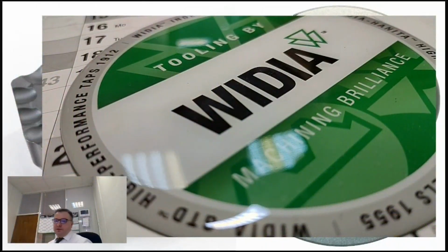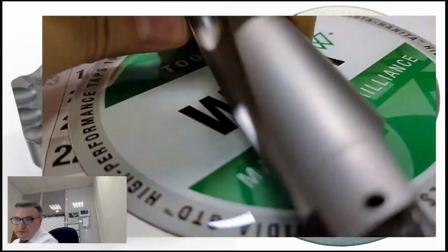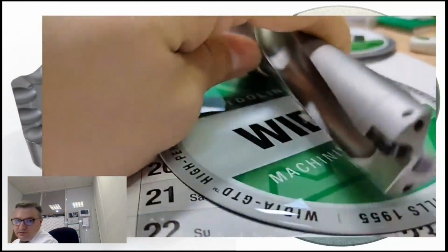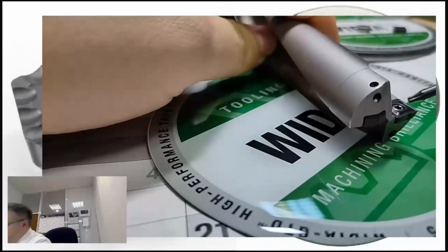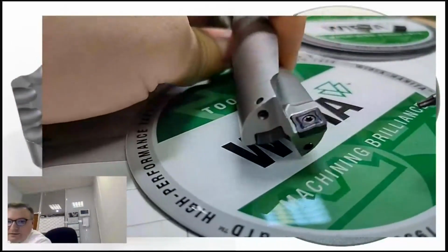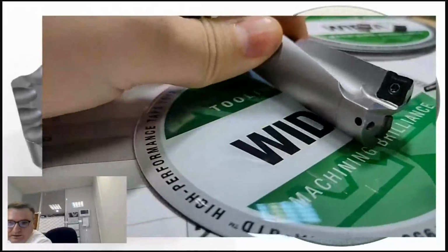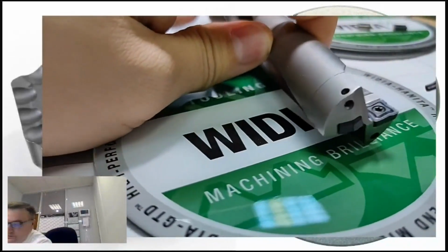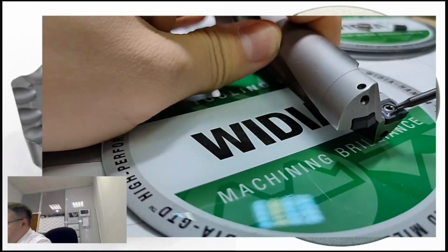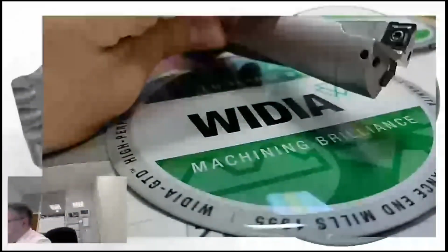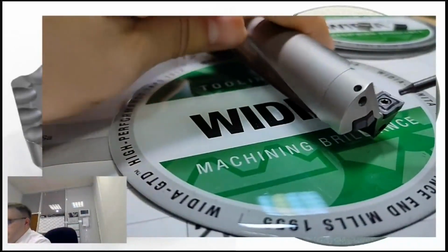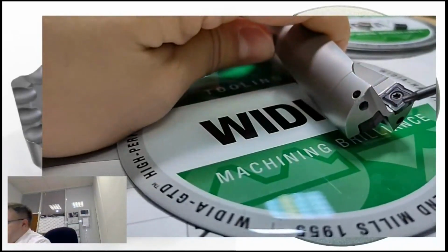And let's look a little bit closer to the top of the drill. Here's the top of the indexable drill. So you can see here the main elements of the drill: the peripheral insert, carbide usually, and the central insert. Their main task is to overlap and to cover the whole radius and, during the rotation, the whole diameter of the drill.